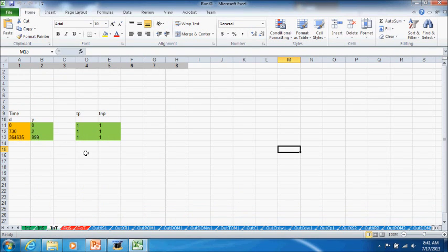There's also an option for specifying time variable input, and this illustrates it here, but it turns out that we're not using any time variable input in this application. It's all steady state. But if you wanted to change the concentration of point source or non-point sources in a time variable manner, you may specify a time series here, so you can simulate fluctuating input. Okay, so that's all the input.